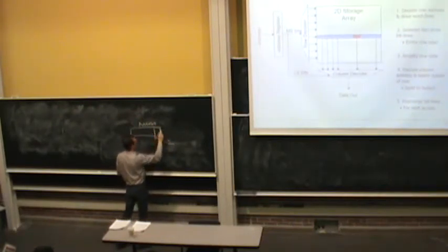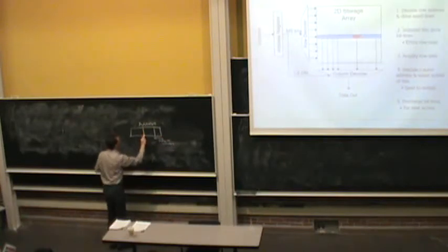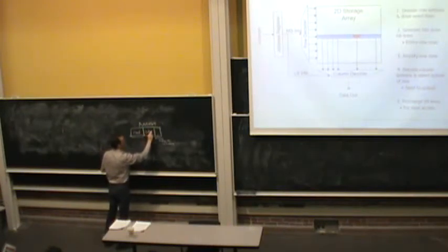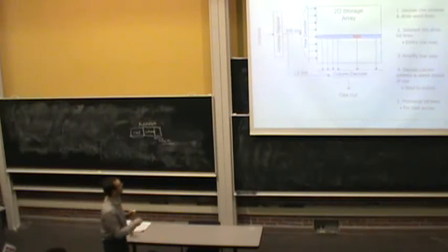These bits you use in your address to select which byte in a column you take. And these most significant bits in the address determine your row. The middle bits determine which column in the row that you want to take out.